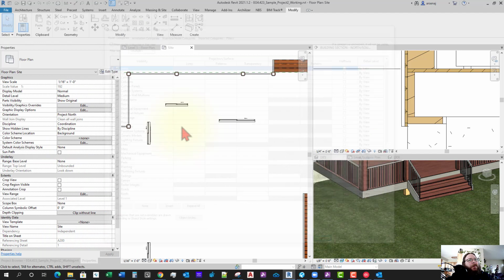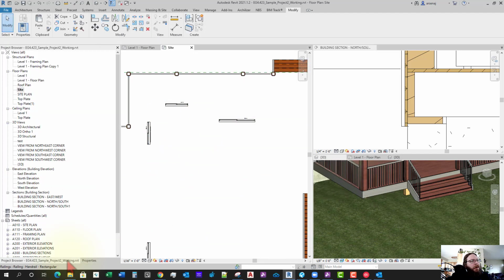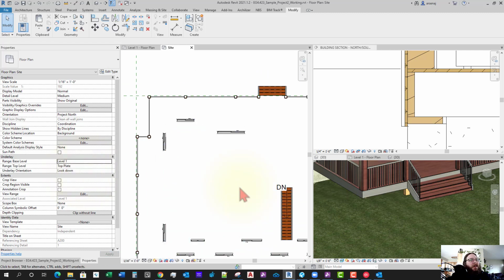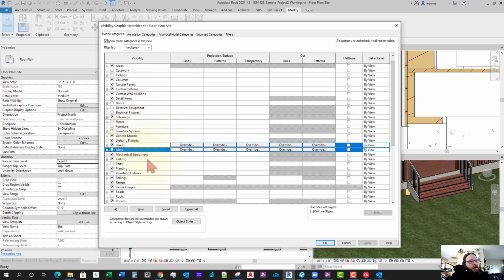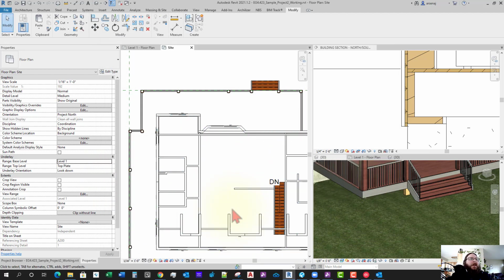It's not as helpful. Yeah, I think that'll be good. What I'll do here is then use an underlay of level 1. I'll leave walls on so I can see my perimeter.